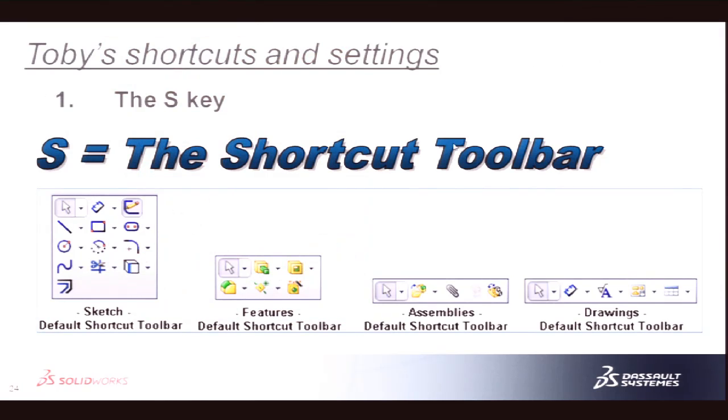So the S key, how many people use the S key? All right, excellent, just about everybody. Soon once all the hands go up, I'll take this slide off my presentations. But until then, everyone should know about it. If you don't know about it, it's S on your keyboard. And you just press that key and it gives you this awesome shortcut menu.